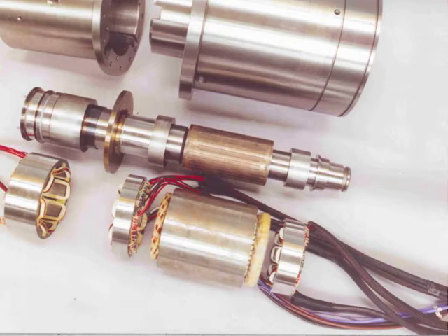The spindle is used to cut metal, and the goal was to support it on magnetic bearings so that it could spin at very high speed and so that its vibration could be well controlled. The magnetic bearings would hold the spindle in place. There would be no ball bearings or fluid bearings. The shaft would be completely controlled by a magnetic field, levitated in place as it spun at 30,000 RPM.